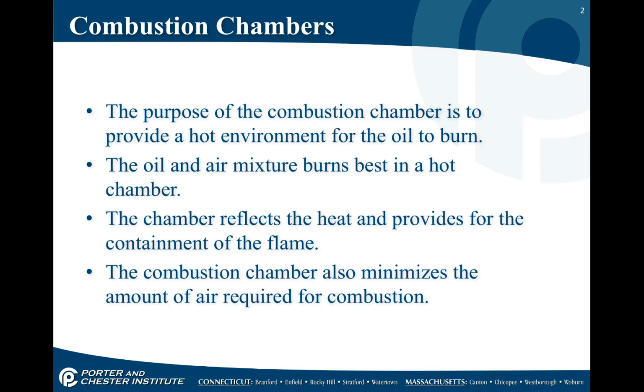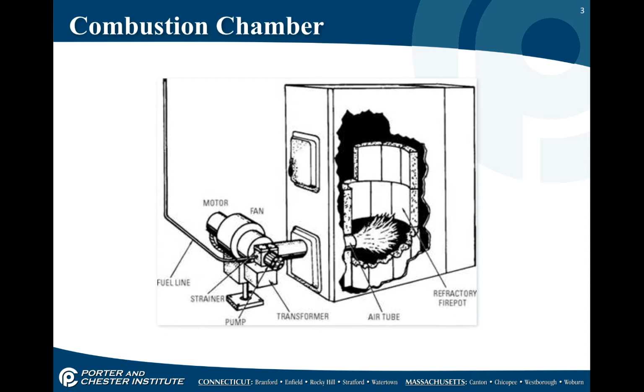If we didn't have the chamber in place, the heat would escape, go up the flue, go into the furnace metal too fast, and we would not have enough heat or air for the combustion process.